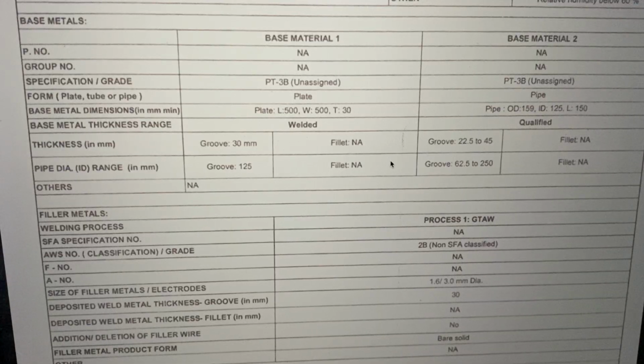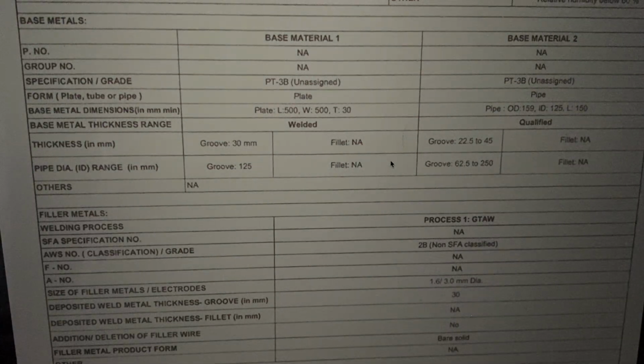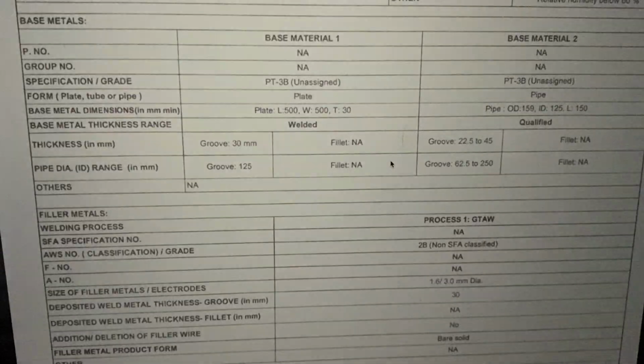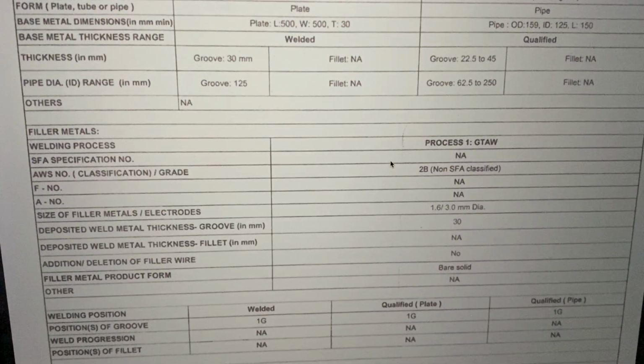All such things will give us a good idea when we review it after the WPS PQR is qualified, and when we have any non-conformances on the job, or want to correlate and anticipate. So that is all given here. Thickness, as I said, is an essential variable, so we have to record it, and the type of joint, whatever it is, also is required to be recorded and monitored.